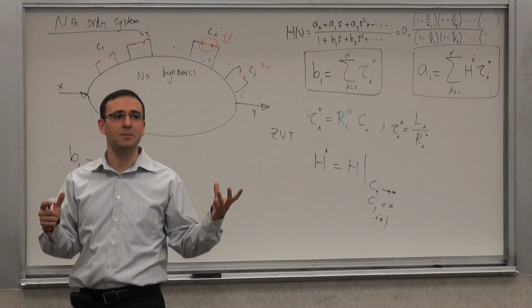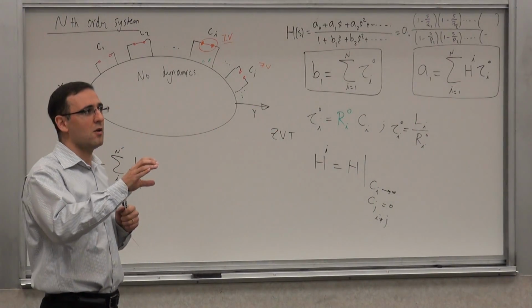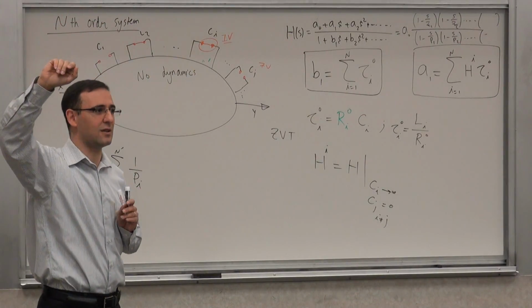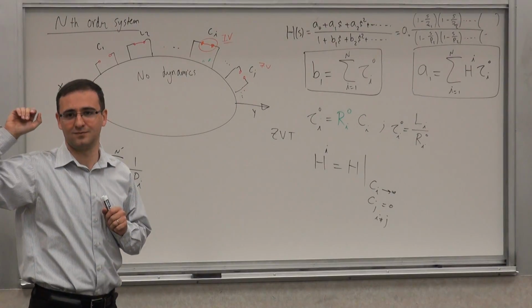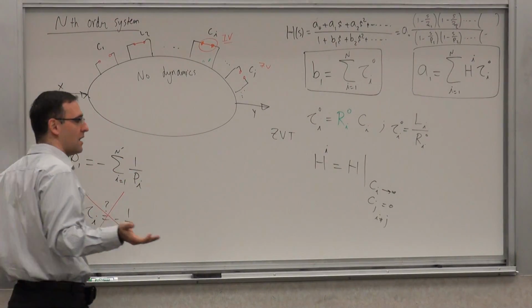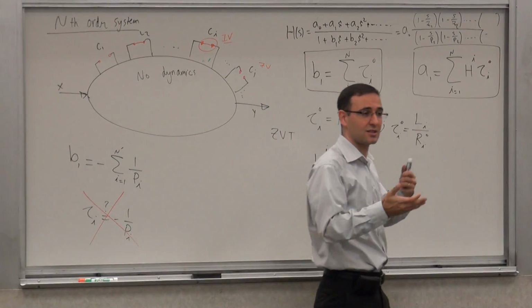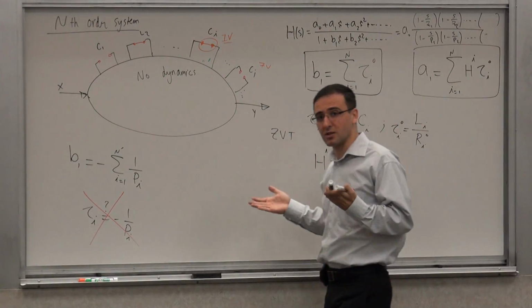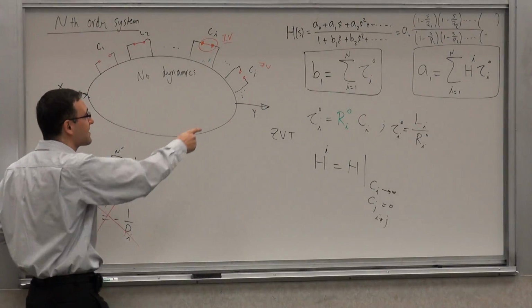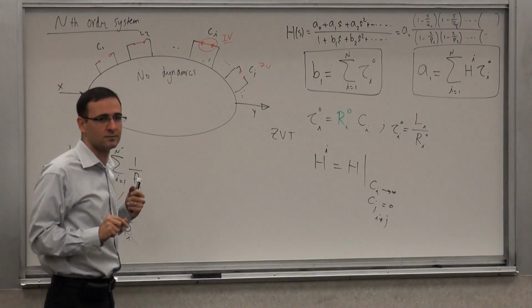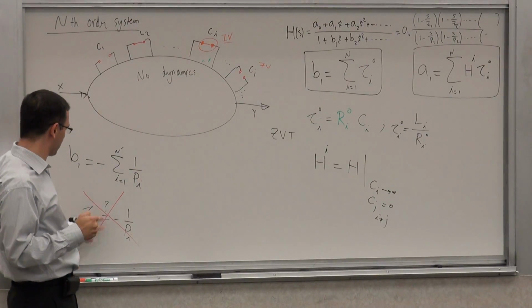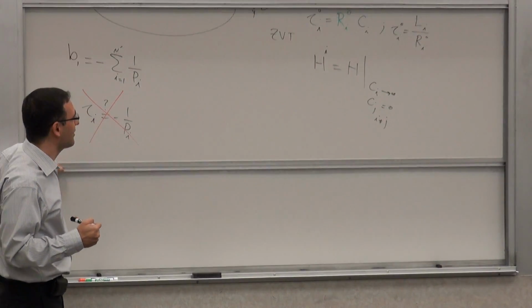And there are a lot of cases where people make this approximation. They say, oh, okay, I have a capacitance here, I have a resistance on this node, they calculate the time constant and say, well, okay, so then 1 over that time constant is the pole frequency. That's wrong. I mean, it's a good approximation in certain cases, but it's not mathematically correct. And a lot of times it's not even a good approximation. So you should be aware of this. But this sum is still very useful. And we'll see how it's useful in a second. But let me show you an example, for you to believe this, and also to see how this is done.